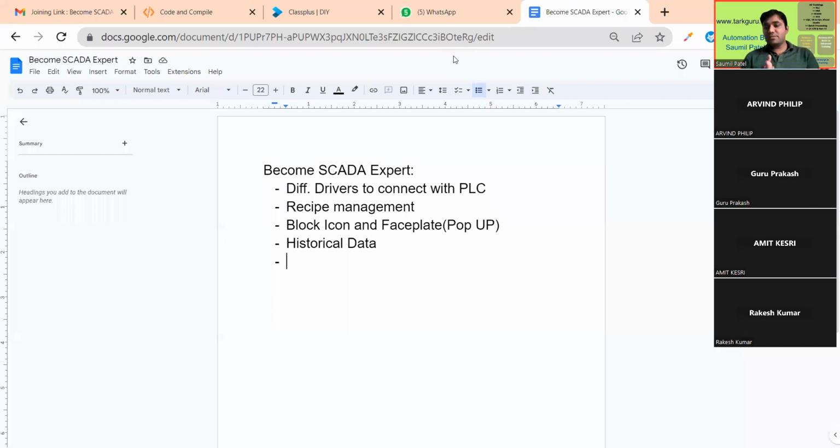For example, if you want to connect your SCADA to the database, because anyway you are going to generate the reports, whatever is going on, whether it's a batch or a continuous process, then to connect with the SQL you require the IPC, you require the PC, and you require the SCADA. HMI cannot connect with this SQL, right? Because HMI has a different platform. HMI is not a Windows based platform, but SCADA is Windows based. You are installing the SCADA software inside your Windows PC. Okay, so your SCADA can communicate with the SQL.